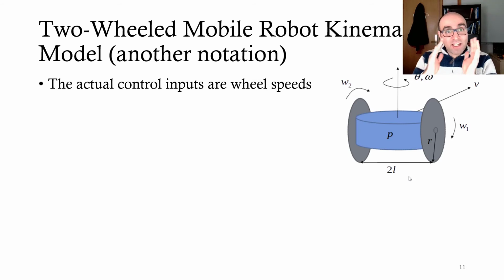So you might assume that VR and VL are the linear velocity of the wheels. No, VR and VL are the phi dots. It shows how fast the angles of the wheels are changing. In other words, they are angular velocities. They are omegas. So in order to avoid that confusion, I will describe them with omega. So omega 1 is VR in the previous slide, and omega 2 is VL.